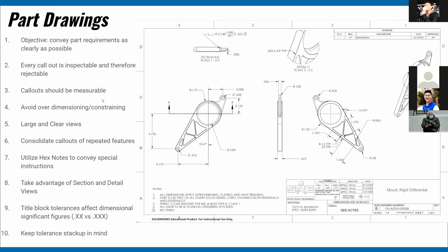If you make a datum off of some arbitrary point or a line that doesn't exist, say if I made a vertical center line for this hole, and then I put an angle measurement off of that line, it's not easily measurable, and it makes a huge headache for quality. Sometimes it could get rejected because they say, okay, I measured it this way and now it's failing, and they have to send the part back.